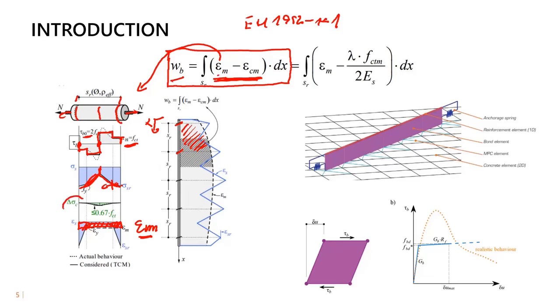As you can see, there is the contribution of the tension. We consider it because there is the mean stress, or average strain, I would say. So we also use the average contribution of the tensile strength in the concrete that steps into the equation, and this is 67% of FCTM, and epsilon cm is this value, introduced in this part of the equation.